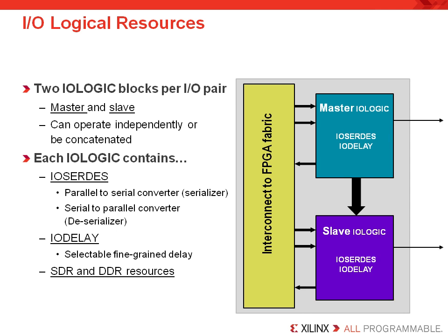The I/O SerDes capability includes input and output SerDes resources. There is an O-SerDes parallel to serial converter for both OQ and TQ. It is arranged as a master and a slave IOB pair to allow for differential inputs or larger single-ended bit widths. So not only can you complete, say, a 6-to-1 parallel to serial conversion, but when you pair these two pins appropriately, you can do larger parallel to serial conversion. For this to be done, an appropriate master-slave pair must be found on the die. You can't just pair any two IOBs and make them a master-slave pair. So you'll need to either check the datasheet or use PinAhead to find out which of your pins are already pre-grouped.